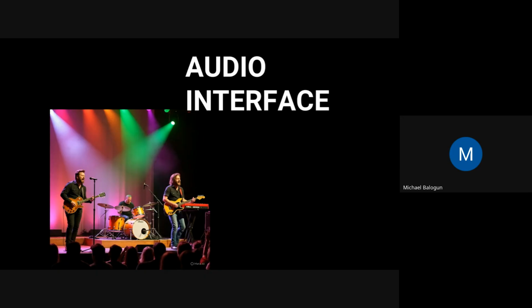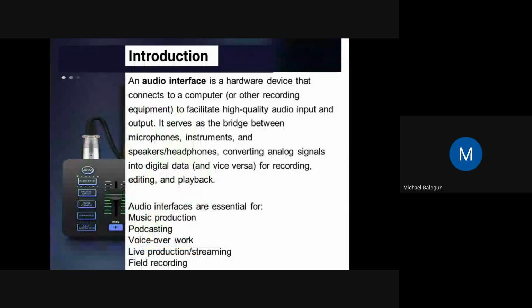We're going to start with the audio interface. Audio interface, and straight I will go into my slide. Introduction. An audio interface is a hardware device that connects to a computer or other recording equipment to facilitate high-quality audio inputs and outputs. It serves as a bridge between microphones, instruments, and speakers or headphones, converting analog signal into digital for recording, editing, and playback.